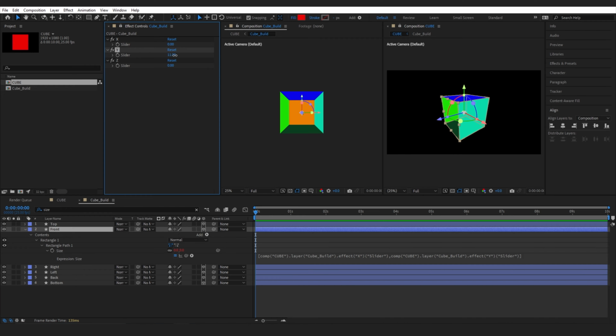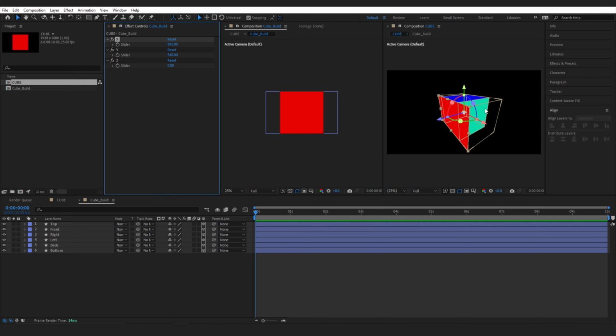And obviously that has made the face disappear for now because this is set to 0. So if we scale both of these up, like that, it starts to come back. So we put it back to 540 on both, and we're back to where we were before. So now when it scales, obviously the blue layer doesn't stick to the red layer when we try to scale it along the x-axis, so we need to get that to stick.